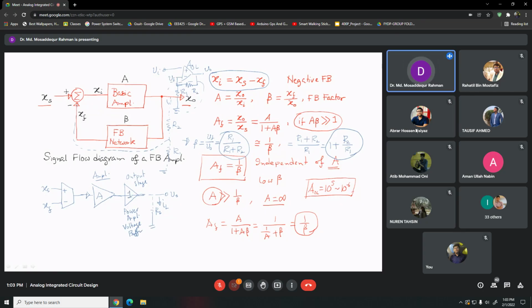It will not increase the gain, but it will increase the amount of power needed by the load, right? Usually when we say large power, it implies large current, so the amount of current will be increased. So we need another circuit here, usually a voltage buffer or power amplifier, that will enhance the power level of the signal.